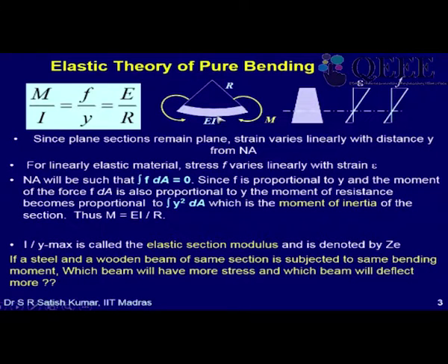We are going to assume that the shear forces are negligible, so it is called pure bending without shear force. We can see here that what would have been a nice straight rectangle has now bent into an arc, and the edges of the rectangle continue to remain along the radius vector.